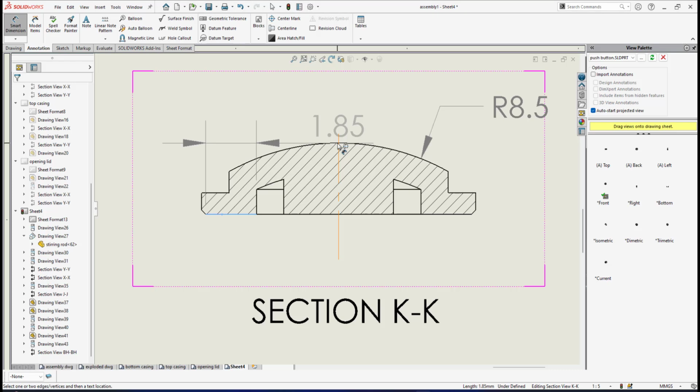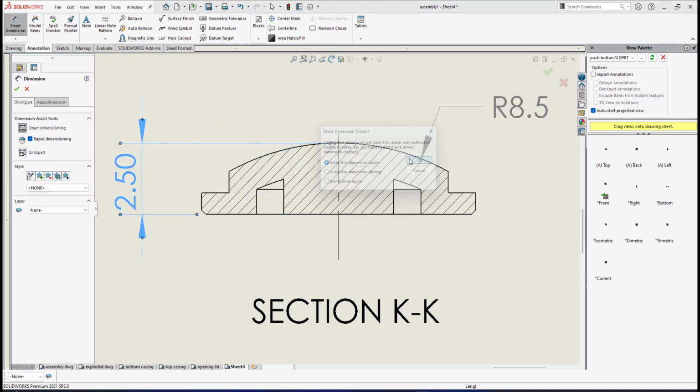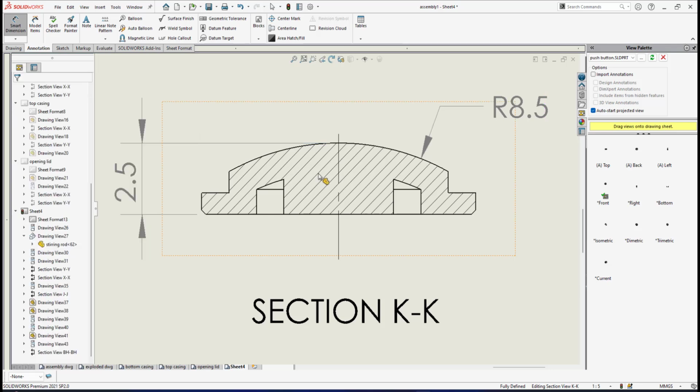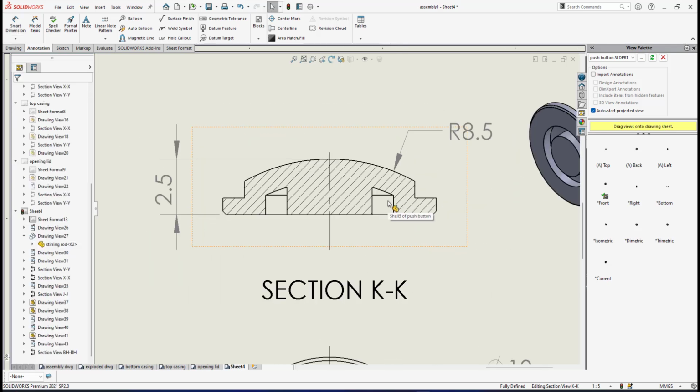And here, I cannot pick the point, so I bring my mouse, it highlights this curve, and I right click at it and select the point, so it detects the point there. So I bring it to this location. I just click OK, and this one is 1 decimal point. Alright, this will be the total height.